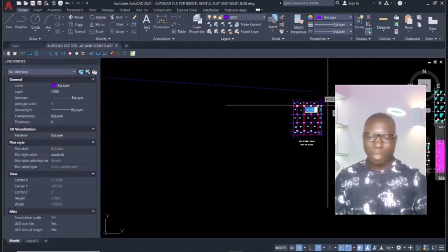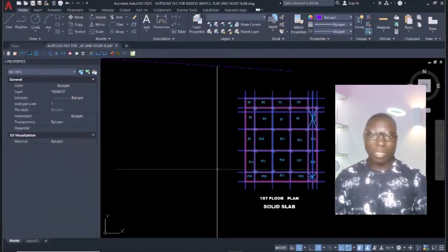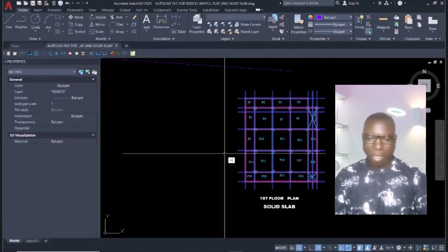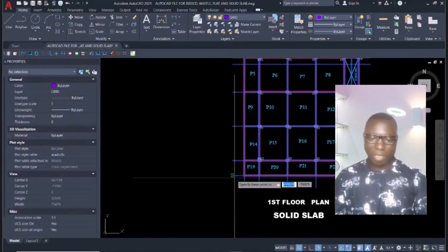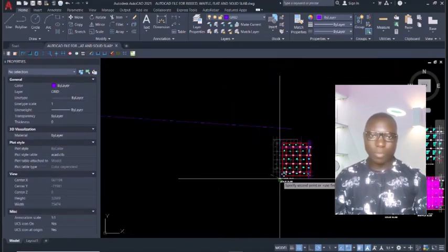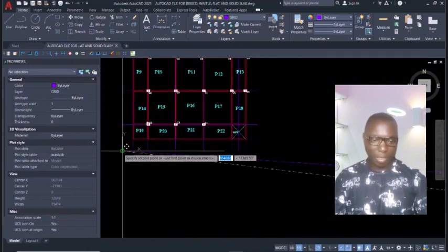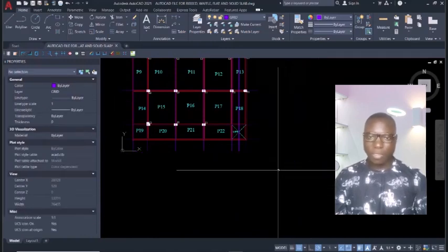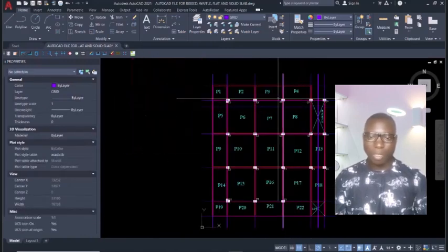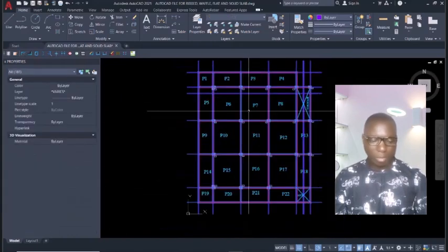Click X-Square, and then I want to copy the grid set out just like this, and then I can also move it. Type M on the keyboard. I trace this edge and pick from this point. Take it over to the origin just like this and I place it here. I'll delete this reference line just like this. Here we go. So I'll highlight all of this right now and then W for write block, enter, and then